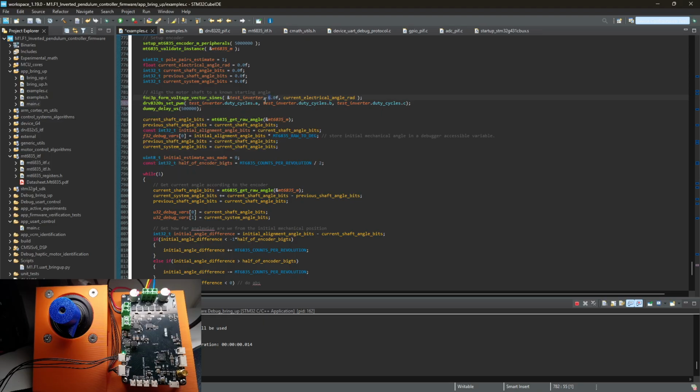Also, no, I'd say 3 is enough, because bigger motors usually have smaller resistance actually. No, sometimes they have bigger, sometimes they have smaller, and putting too many volts into such a function can lead to us burning the motor the same way we did an hour ago, where I had to quickly click off my power supply because it was sending an amp and a half through a single phase.